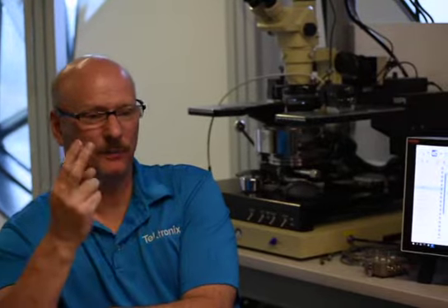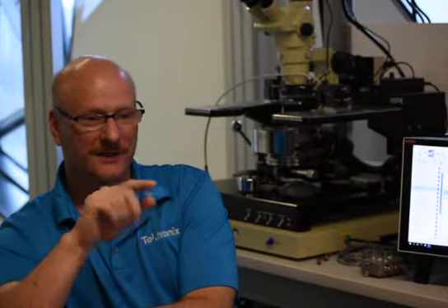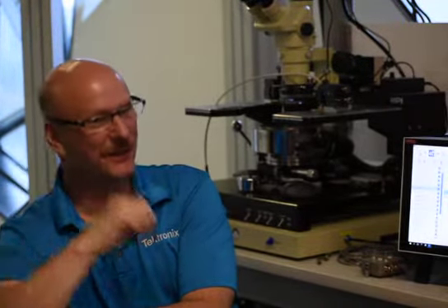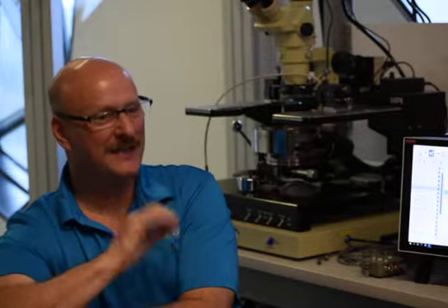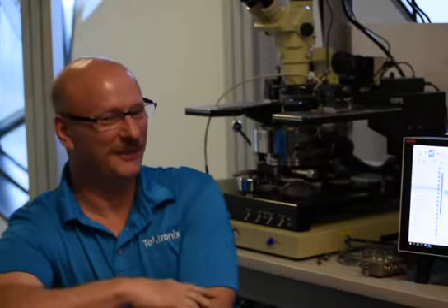And what about the preamp? Yeah, we have one empty spot in the CVIV module. If you want to order one preamp, that should also be calibrated. It has to be calibrated with the SMU. The preamp and the SMU are paired. They're tied together. You can't put a preamp 2 on SMU 1. It says on the preamp SMU 1, so it has to go to SMU 1. It's that sensitive. It's a very tight calibration.